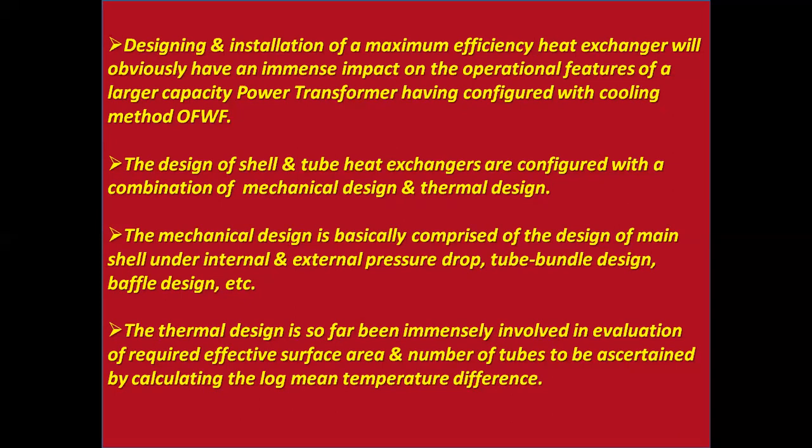The mechanical design basically comprises the design of the main shell under internal and external pressure, tube bundle design, baffle design, etc. The thermal design is involved in evaluating the required effective surface area and number of tubes, to be ascertained by calculating the log mean temperature difference.